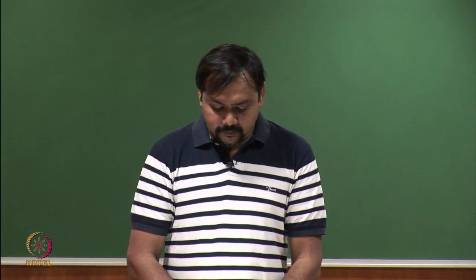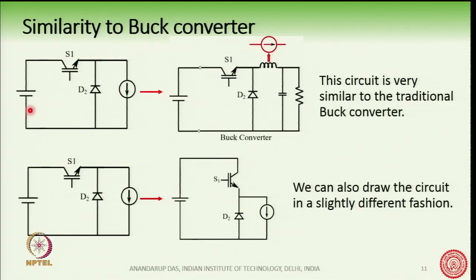Now, the circuit which we have so far developed is this one, with the switch, diode and the voltage and current source. Those who are a little bit familiar with power electronics will immediately see a similarity of this circuit with a buck converter.